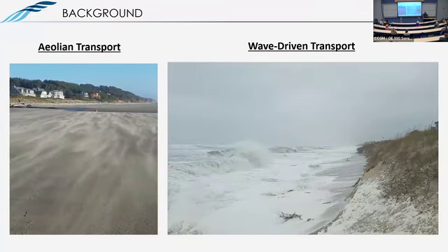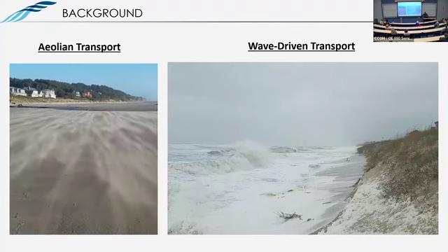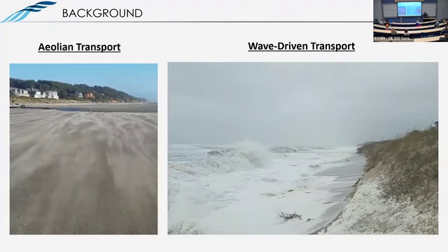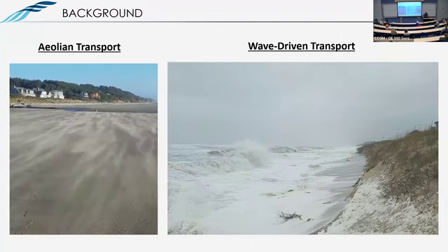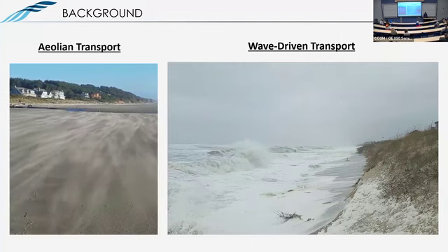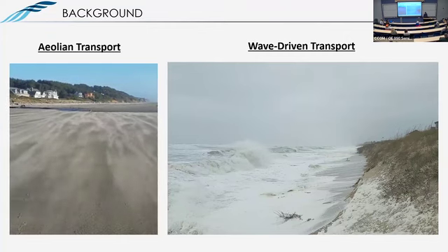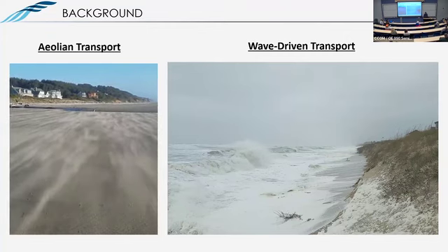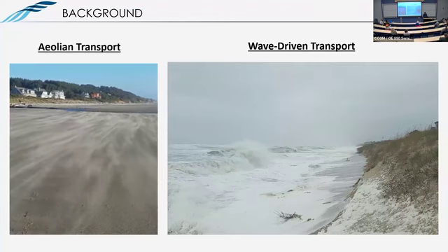And there's a lot of evidence that turbulent boundary layers strongly depend on how they were generated, the initial conditions and all that. So with your data, it's great to see it all cluster and sort of collapse. But did you notice some significant differences in transport rates when you modified these initial conditions on how the boundary layer actually evolved and came to you?